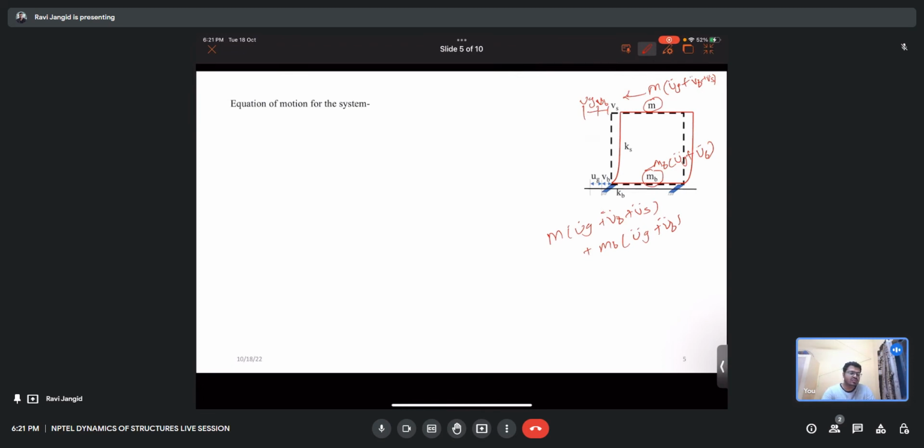Now we are cutting our structure from here. The stiffness force of the isolator will only take, note this, whatever the internal deflection will not be taken care of by this isolator stiffness. So that will be the force by the isolator, K_b times v_b, the relative displacement, not the total, because the ground motion u_g is the rigid displacement, in which our structure will not deform.